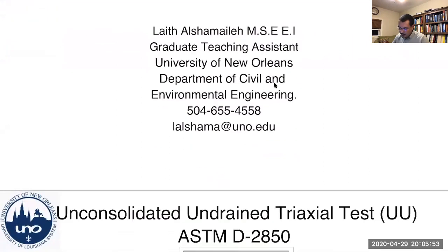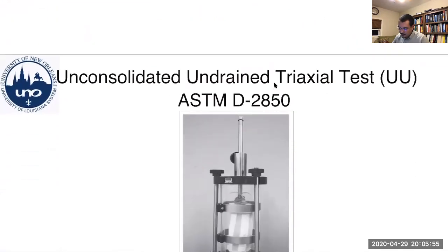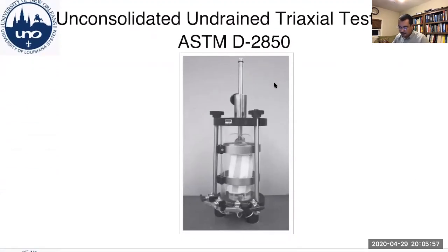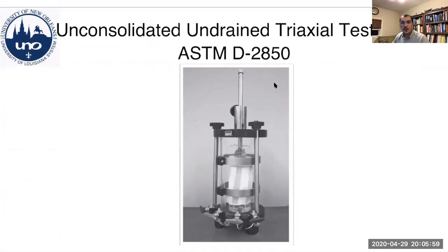Today's soil mechanics lab is going to be about the triaxial test. This is another test where you can get a shear strength value for cohesive soil, meaning silts and clays, or cohesionless soil, sand. So it can be performed on both.